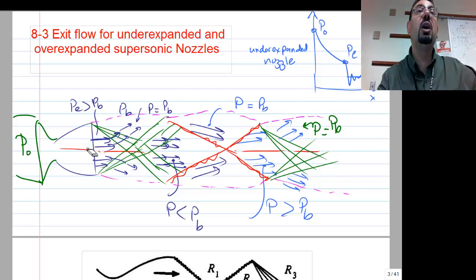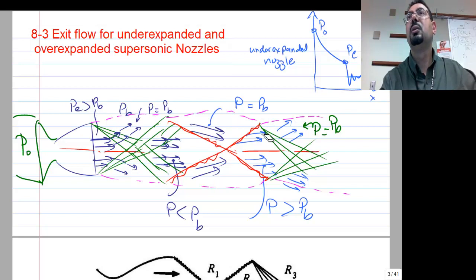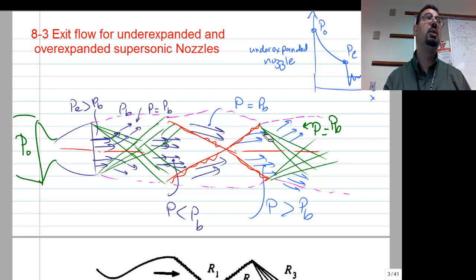But here is an easy way also to realize what's going on. At the center line, it's as if it's a wall. The center line is really like a wall separating the two flows. So the wave reflects with its own type. An expansion fan reflects as an expansion fan. An oblique shock wave reflects as an oblique shock wave. But at the free boundary, at the pressure boundary, the wave always changes its shape. So expansion becomes oblique, and oblique becomes expansion. Alright? Does this make sense?